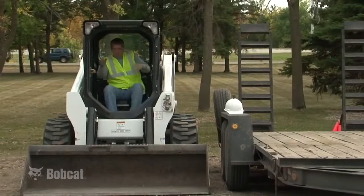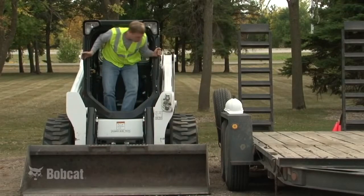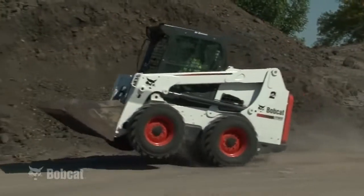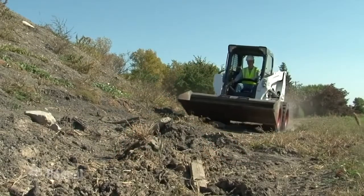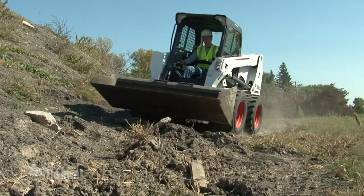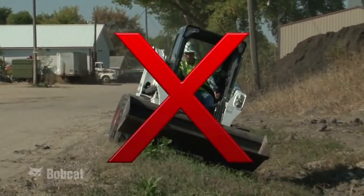Never stand, lean, or reach out of the front of the loader when the engine is running. A steering control or hydraulic control could be activated. Don't make any sudden stops, starts, or turns. Again, operate the controls smoothly. Avoid rough terrain if possible. Be careful on slopes and avoid traveling across steep slopes.